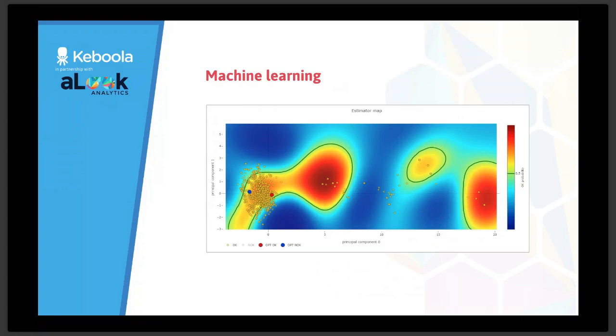And not only the optimal setting, but you also need to have some kind of lower and upper boundaries for individual user setting parameters. Because it's not easy to set a temperature right to, let's say, 260 degrees, because there will be some thermometer or heater going on and off based on the temperature. So the parameters are oscillating, and therefore you need to provide something that is called a process window, which is exactly the lower bounds and upper bounds for individual user settings.